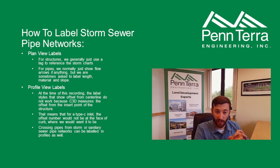As of right now, at the time of this recording, our label styles for the offset from center line do not currently work properly for pipe networks because they label to the insert point of the structure, which on a type C inlet is not at the face of curb, it's the center of the box. So I haven't been using that offset style. If you run into a comment or something where someone requests it, we can work through that, but for right now I would just stay away from it until a fix is made.